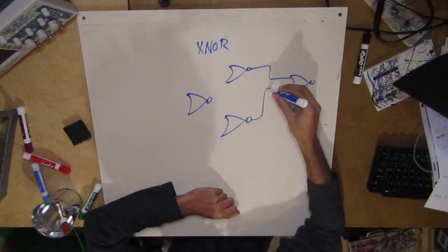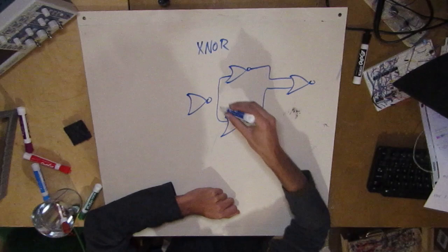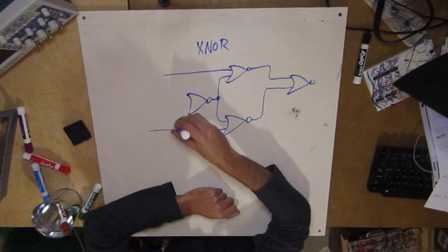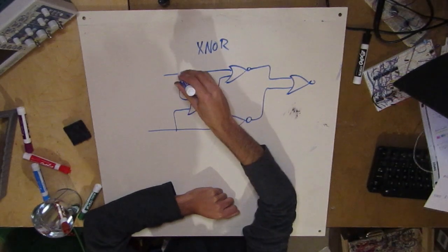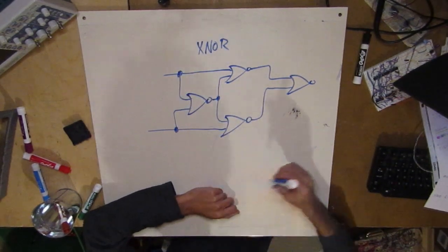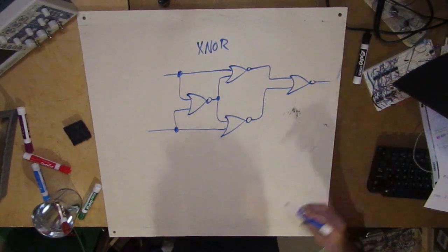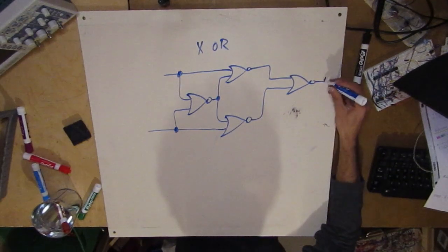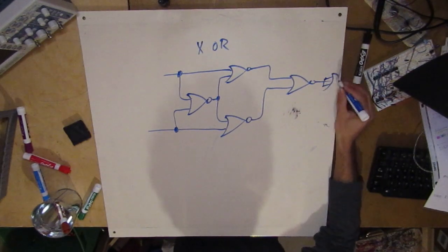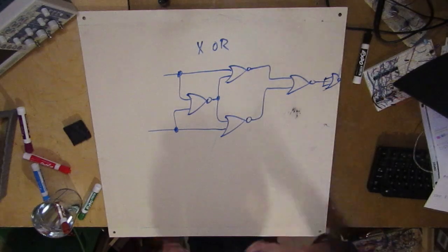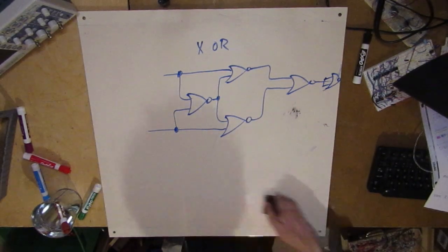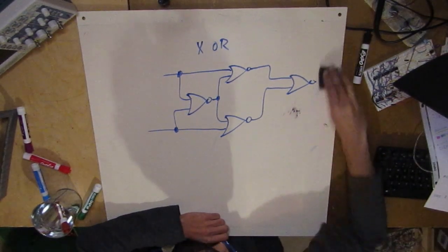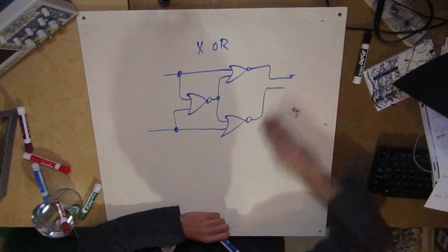So I find it really cool that these patterns arise, like opposite version patterns. This is what I really like about digital electronics, the inversion patterns. So this is an XNOR. Now I could turn this into an XOR by chaining that inverter to the end. So this inverts it, then it's an XOR. But what if I want to make an XOR in a different way using 5 logic gates, and it follows that same pattern that we saw with the NANDs?